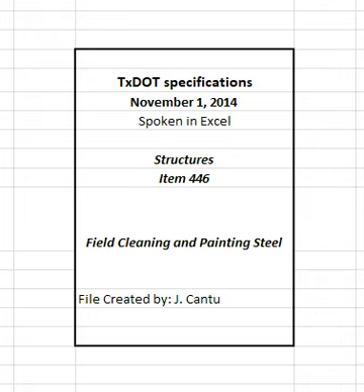Store waste collected in containers that comply with 49 CFR Part 178. Seal containers containing waste each day before leaving the job site. Test a representative sample of waste using EPA Test Method 1311, Toxicity Characteristic Leaching Procedure, TCLP, to determine existing metal and organic content.